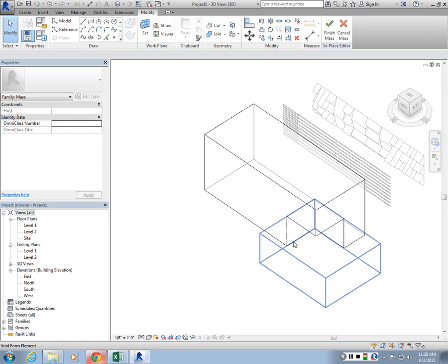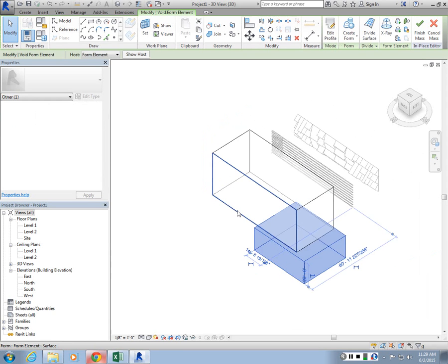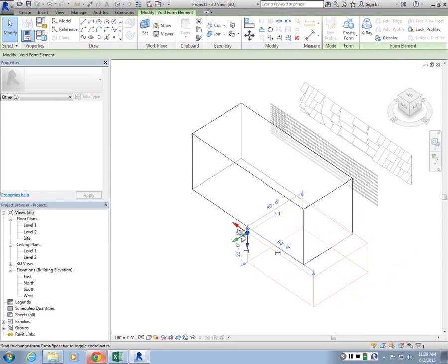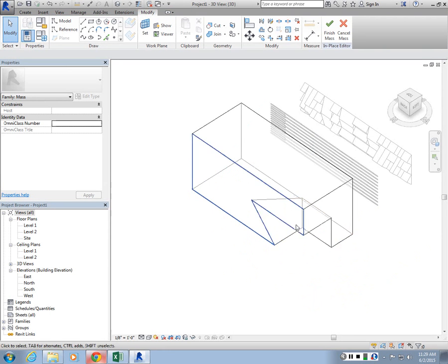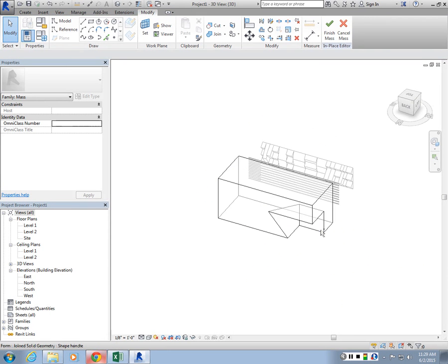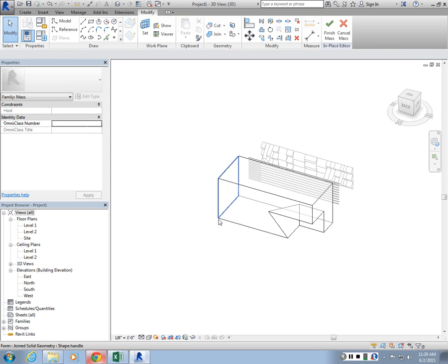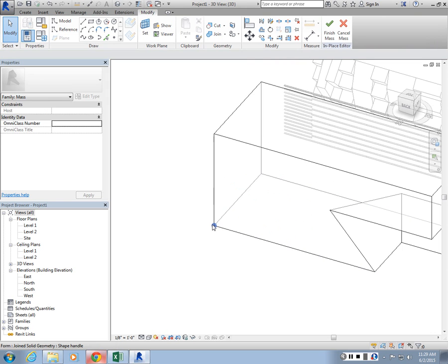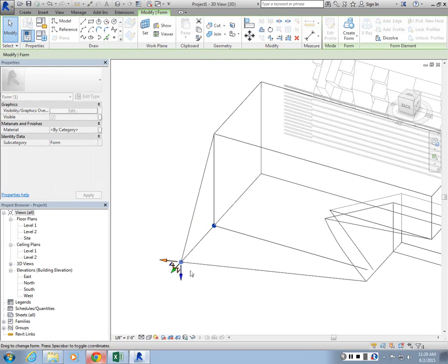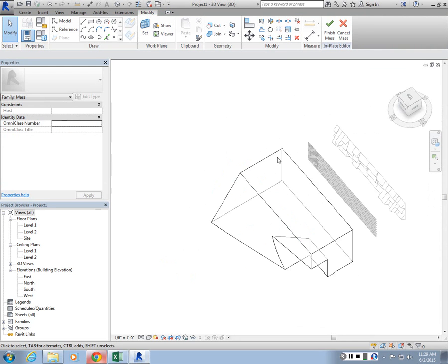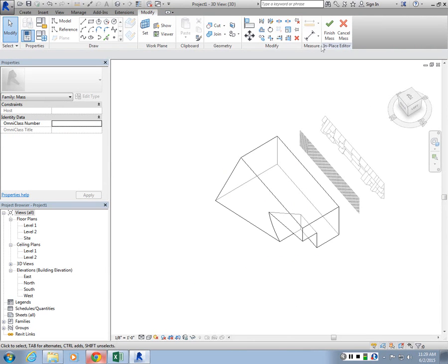And then if you want to edit it, you can use the tab key to iterate through the elements you created. And then I can choose its vertices as well. I can move the void form extrusion and start customizing the shape of it. Here, for instance, I can move it here too. So it's basically a dynamic modeling environment.